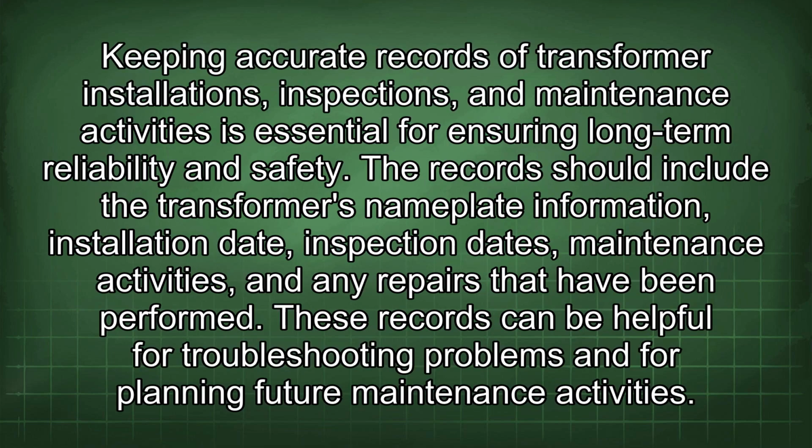Keeping accurate records of transformer installations, inspections, and maintenance activities is essential for ensuring long-term reliability and safety. The record should include the transformer's nameplate information, installation date, inspection dates, maintenance activities, and any repairs that have been performed. These records can be helpful for troubleshooting problems and for planning future maintenance activities.